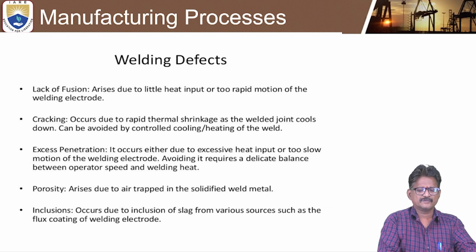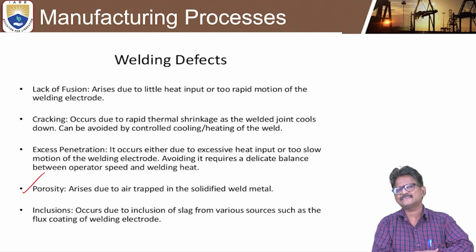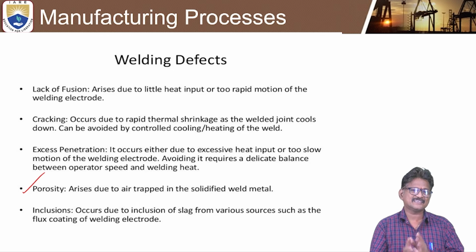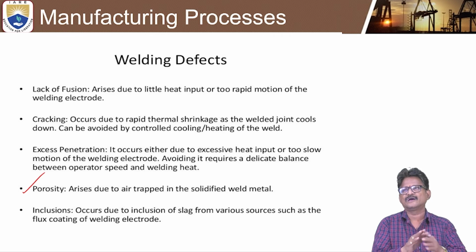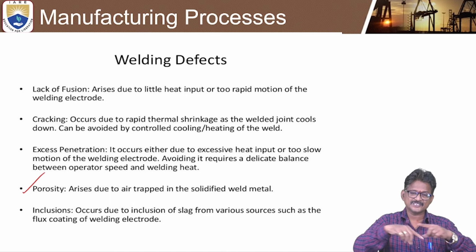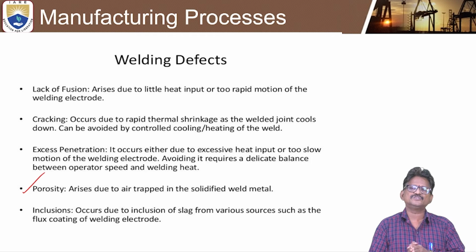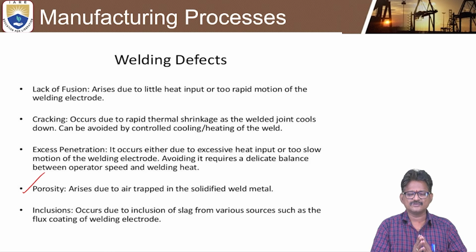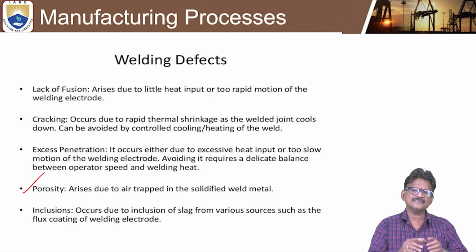Okay, coming to porosity. Even in the casting process, the material is porous in nature. Even if the sand preparation is properly made, you will definitely have some porosity. But here, it is due to air trapped in the solidified weld metal, especially when welding is performed in the open, where air particles and dust particles are present. That is why, while performing the welding, some kind of cabin should be used. If you are not using a proper cabin, obviously there will be porosity, trapped air, and some bubbles in that weld metal. So in order to get good quality, you should maintain a box or good cabin for performing this welding process, without disturbance from air and dust particles.